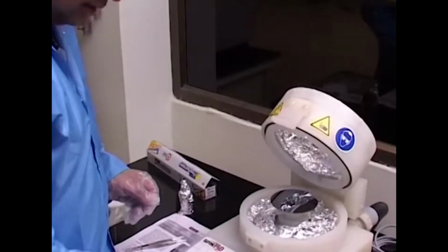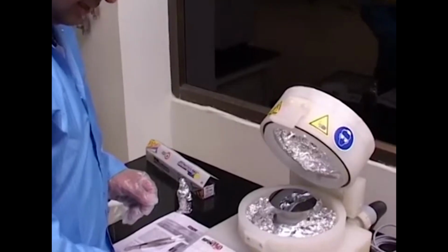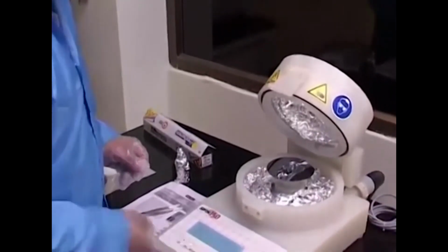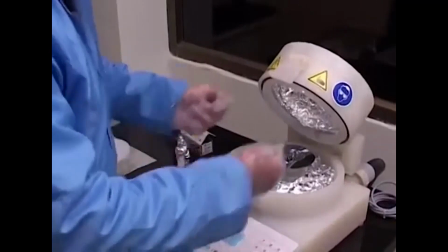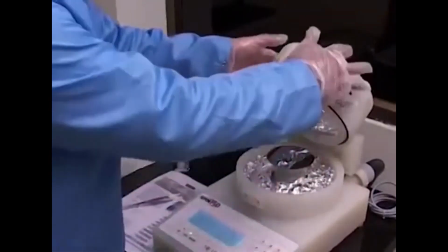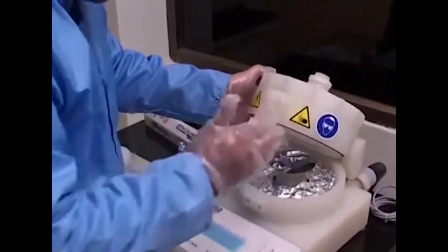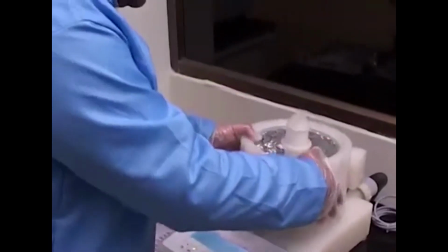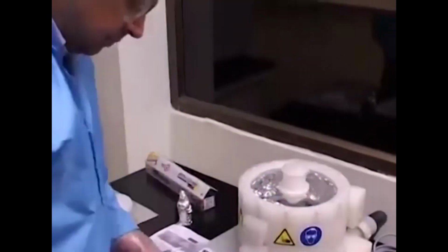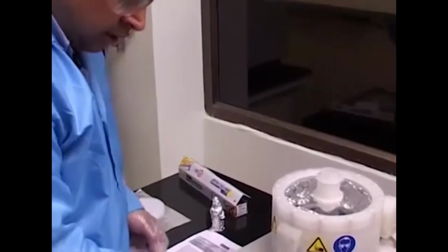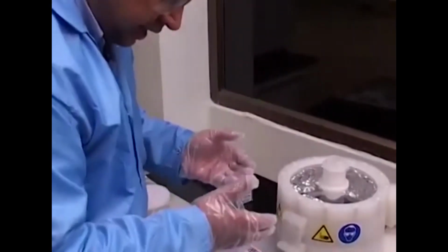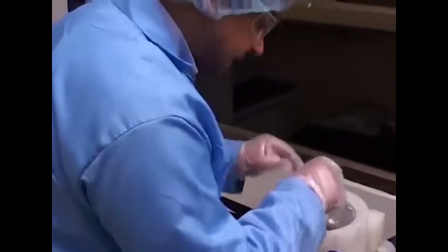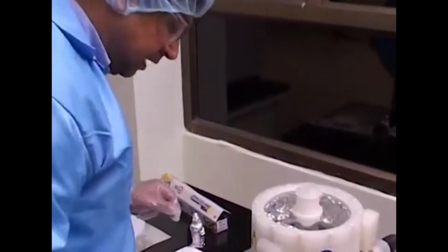The light would come on, as you can see here. This is in the on mode. So basically the vacuum pulls the wafer so that it can sit onto the spin table, and then we also have to see whether the wafer is centered. The way to do it is basically close the lid of the spin coater and turn this RPM on so that the system actually starts rotating, and see from this top transparent area whether there is any wobbling in the particular wafer.